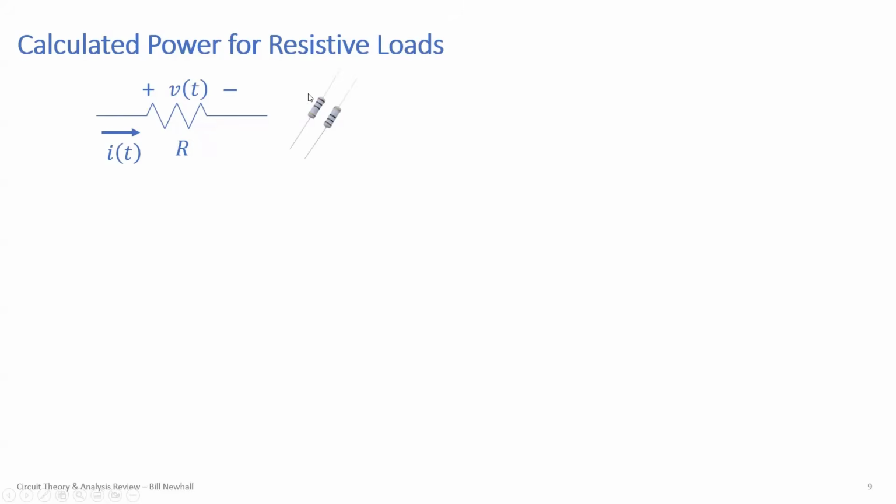Okay, so I have a time varying voltage and a time varying current defined here. Whenever you calculate power for Ohm's law, have the reference direction for current pointed into the positive sign of the reference polarity for voltage. If you need to flip those to make that happen, then I would write negative in front of the variable that I flipped. If you want to see example calculations, see the review videos for power calculations.